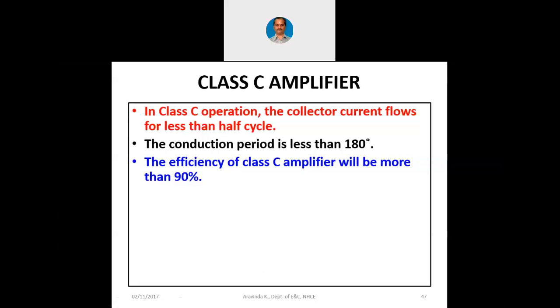As I already told you, only audio amplifiers require a correct shape of the waveform. Radio amplifiers do not require a correct shape of the waveform. That is because they work like a carrier waveform. They are the modulated waveforms, whereas we will have a signal which is a modulating waveform. The modulating waveform shape has to be exact. The modulated waveform is going to undergo anyhow change in its amplitude. So its basic amplitude as a waveform is not really very important.